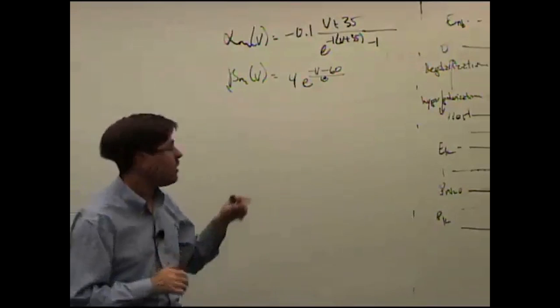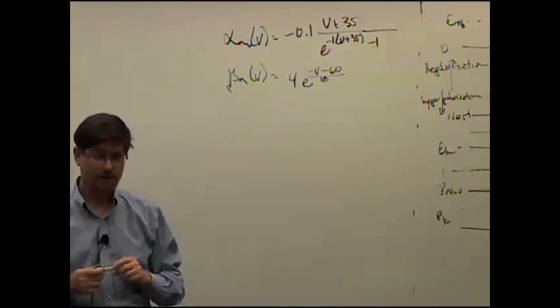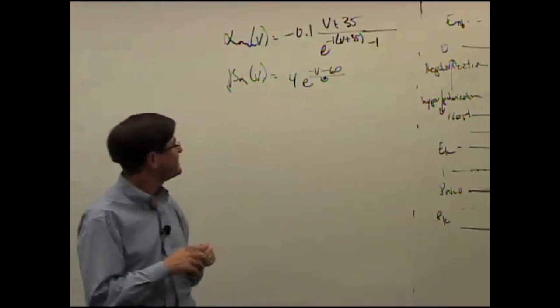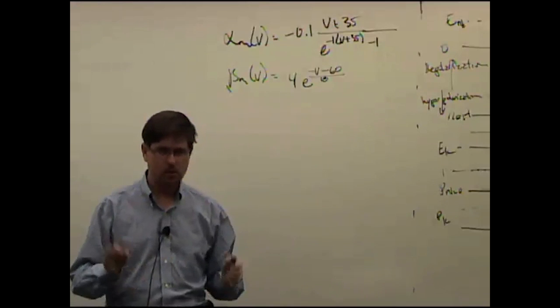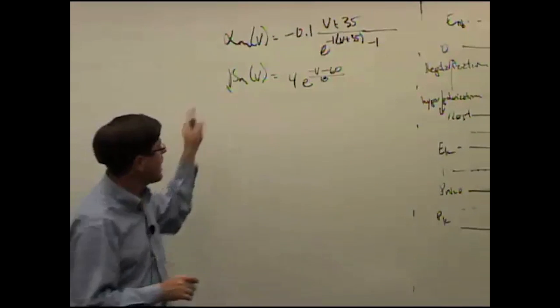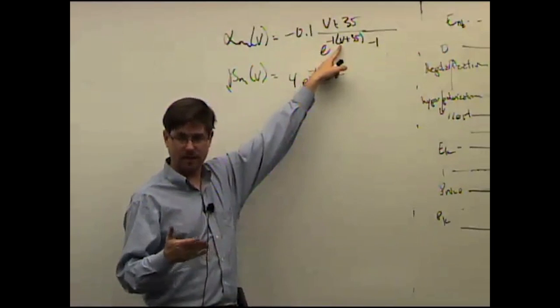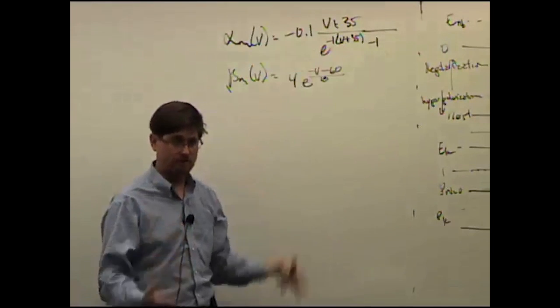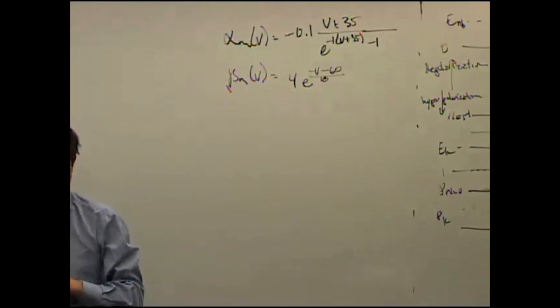And you'll find in almost all the alphas there's some kind of pole in the equations. And the poles are a real pain. You need to use special integrators to run these equations, because you'll get a value at some point very close to 35 millivolts, and the equations are going to explode on you. You have to have an integrator that can deal with those explosions.